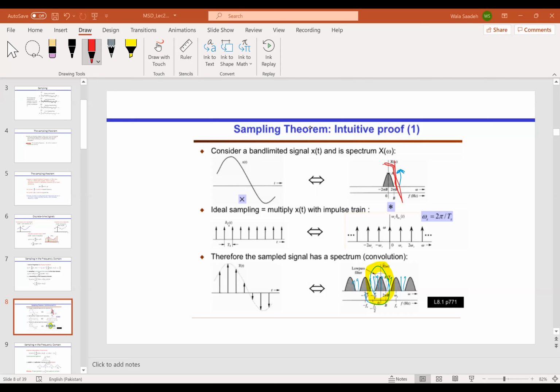Yes. So basically, again, if there is any signal that is beyond your band of interest, once you do sampling, it will also be sampled the same. The sampler does not understand that this is an interference that I should reject. It will consider it as just a signal that is coming to it. So it will do the same exact process of sampling. So it will sample this noise, and it will come within our band of interest.